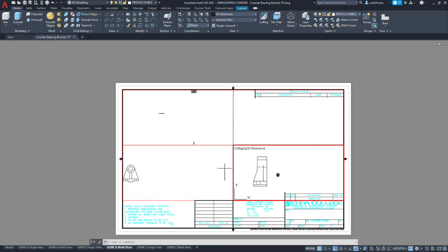So this particular one, we don't really want it centered. You want to avoid in general putting anything right above where the parts list would be, or right below where the revision block is going to be. As the drawing is revised, this will get longer, and if this has multiple parts, this could be a premium space that you need for future revisions.